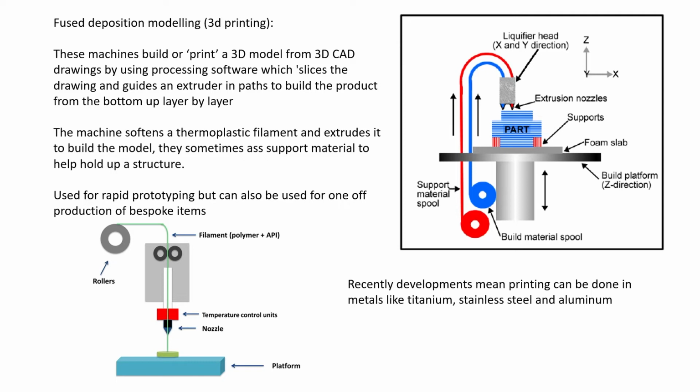Once you've got your 3D model, you'll export it as what's known as an STL file. It then needs to be sliced in a slicer. We typically use something called Cura, which is just a piece of software. Essentially, what that does is literally slice your model into loads and loads of layers.